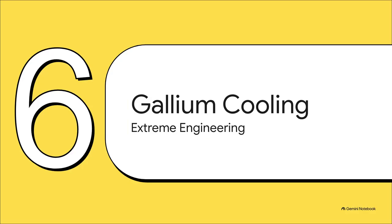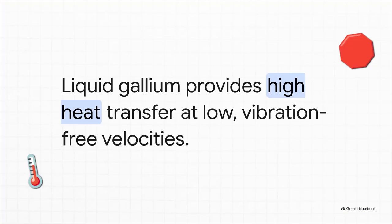For our final act, Section 6, Liquid Gallium Synchrotron Cooling, Extreme Engineering. We are now pushing into the absolute extremes of engineering to cool quantum-level optics. Inside next-generation X-ray facilities, incredibly delicate silicon crystals are getting hammered by intense beams, creating thermal loads up to 20 kilowatts. That's a huge amount of heat. Normally, you'd use water to cool things down, but you'd have to pump it so fast that the turbulent flow would physically vibrate the optics, ruining the precision of your photon beam.